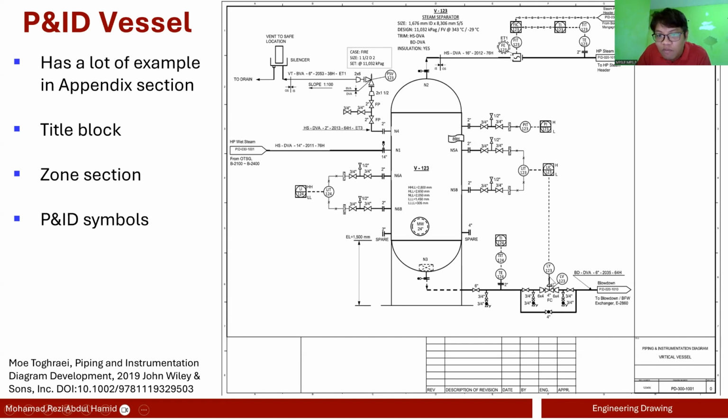As you can see here, this control valve has this line where it is pneumatically operated. So opening and closing of the valve is controlled pneumatically. And then passing through this control valve, you have a reverse reducer here to increase the pipe size again. You have another drain valve and then a gate valve, and then it goes back. So these are the 4-inch bypass valve, 4-inch globe valve, or your bypass line.